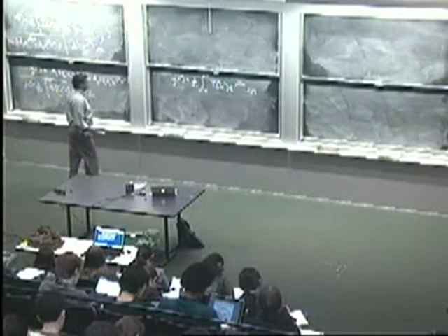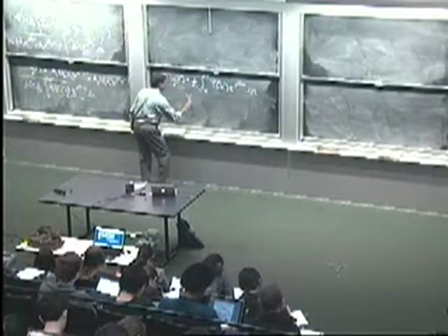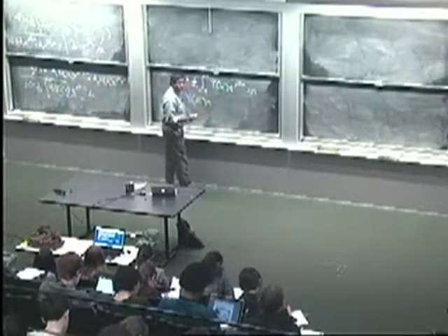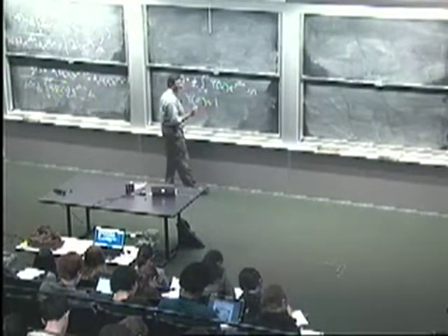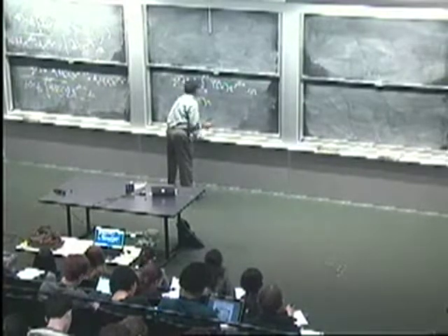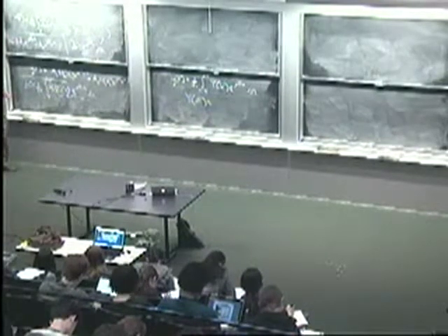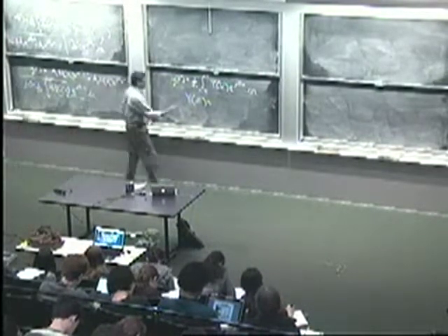If you compare the two, what do you discover about the DTFT of the output? Where's the weighted combination? It's whatever multiplies e to the j omega n in this expression, right? So it's just going to be H(omega) X(omega).